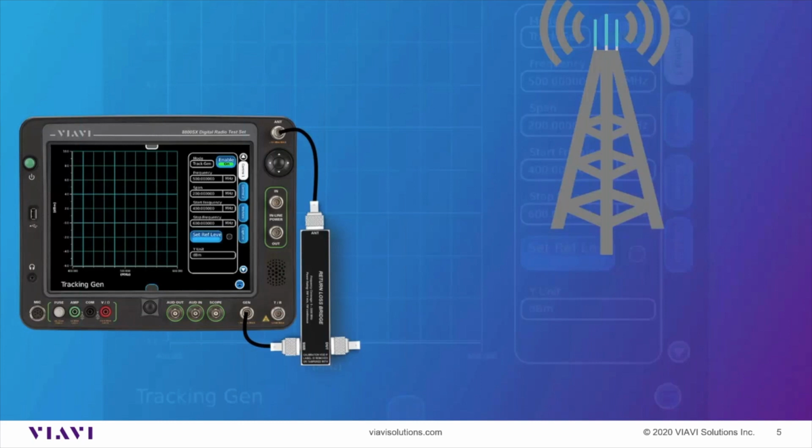So it's kind of a mouthful, but basically we just sweep that line, and anything out there that is an impedance mismatch is going to reflect that signal back, and we'll see that on our trace on our tracking generator.